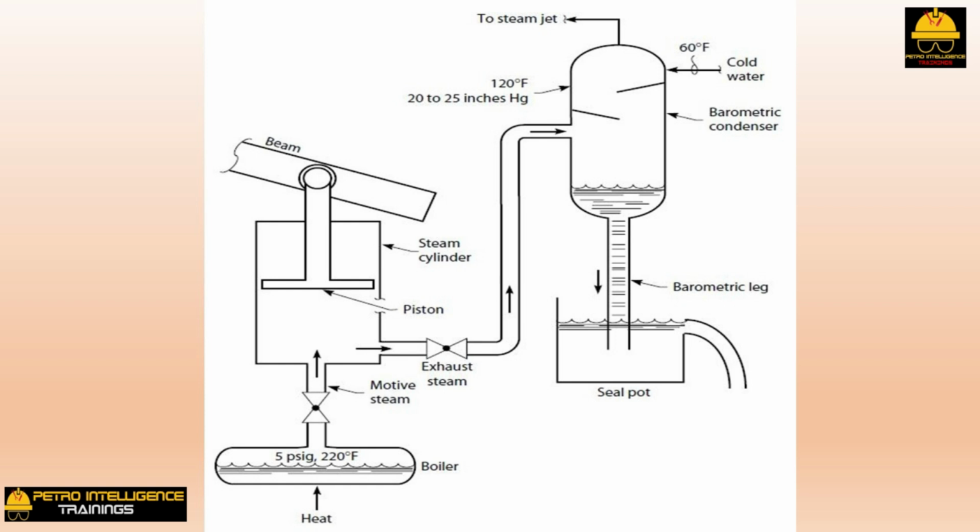Well, if the steam did not really push the piston up, what did the steam do? The answer is, the condensing steam pulled the piston back down. As the steam condensed, it created an area of very low pressure below the piston as shown in the picture. This low pressure sucked the piston down. The colder the temperature at which the steam condensed, the lower the pressure at which the steam condensed. The lower the pressure in the steam cylinder, the more forcefully the piston was drawn down.